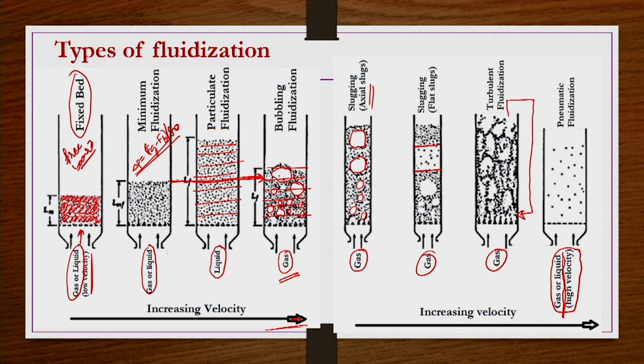Other properties also matter, sometimes particle structure and the nature of the particles; they all have an effect on the flow patterns in general, but generally we can experience this kind of behavior. Depending on the size of the particle as well as the density difference between the particle and the fluidizing medium, the particles are categorized as A, B, C and D type particles, and mixed behavior is also possible in general.